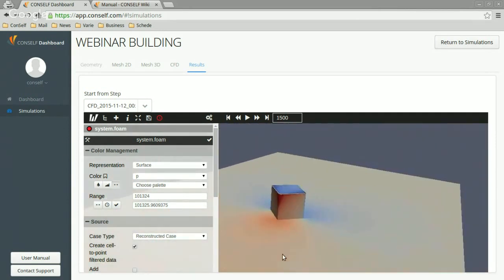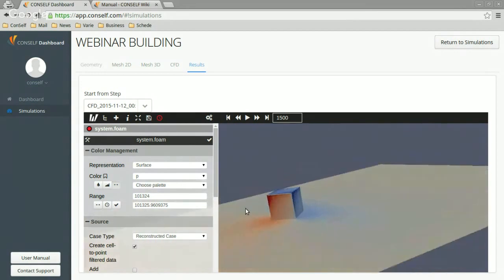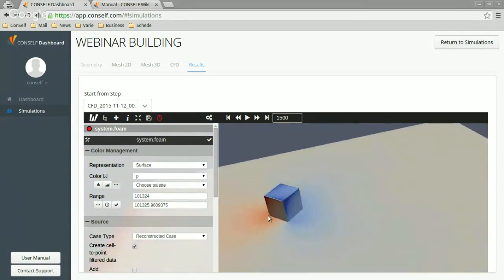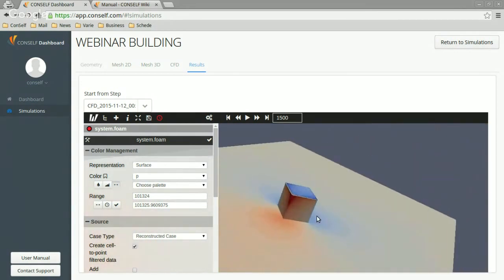Obviously, it's quite simple, this geometry. Obviously, the highest peak is in the front part, while the lowest one is in the back part. But something important, you can integrate the pressure on these surfaces to obtain the structural loads. Again, it is a very simple case, but you can apply the very same approach with a complex geometry and you will find the very same result.